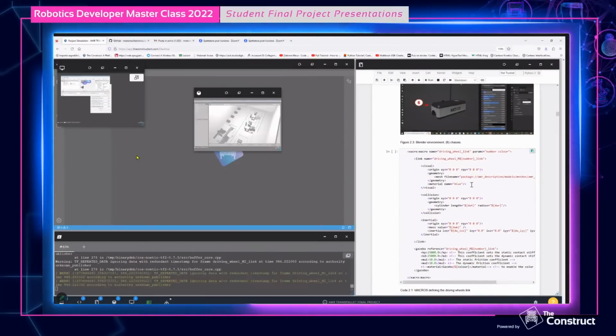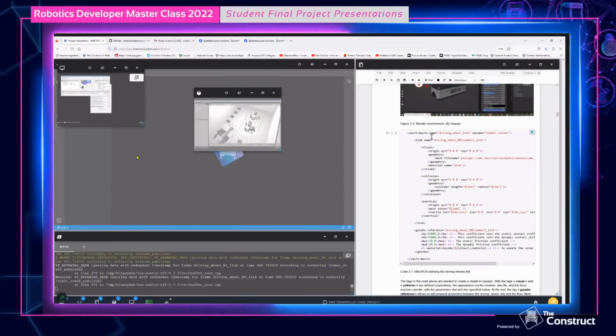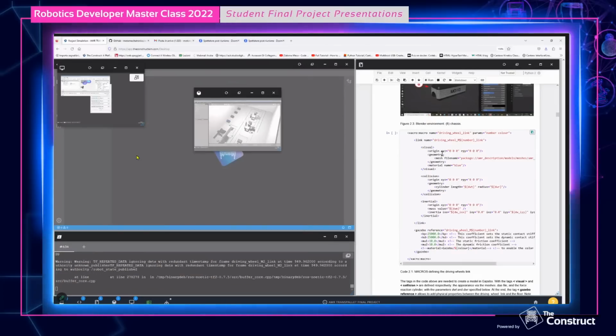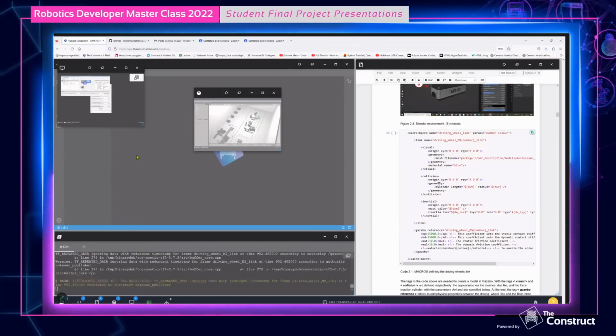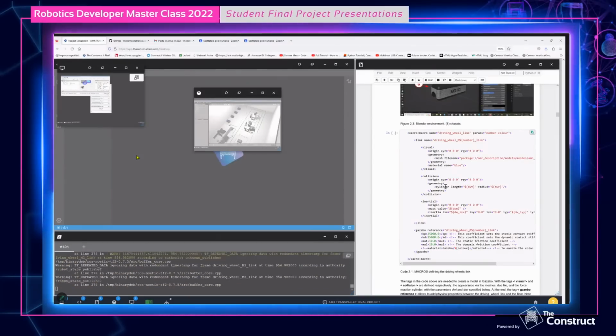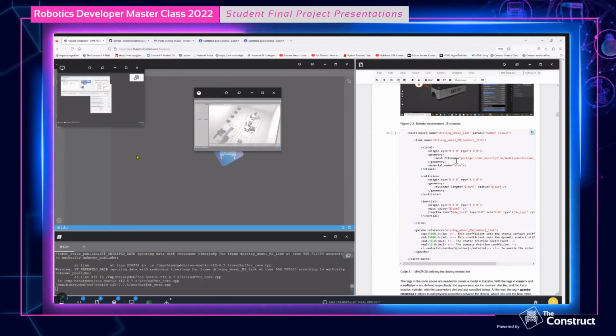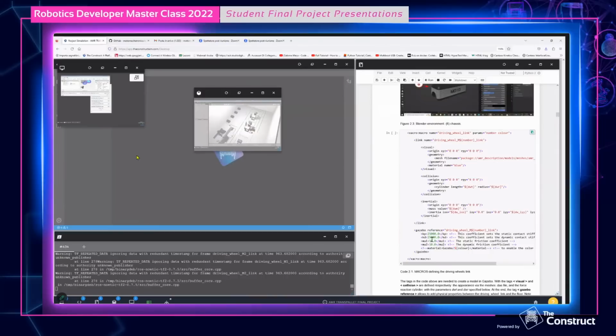And here in this part of code, you can see the Xacro file, with the parts useful to create the geometry, the collision, and inertia, which is important because the robot moves in a physical environment like Gazebo, and the visual. At the end there are the physical properties of the floor,